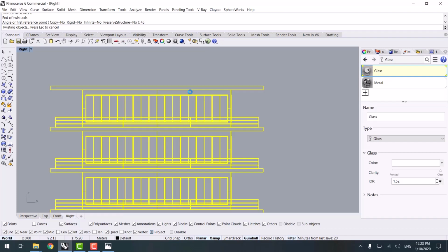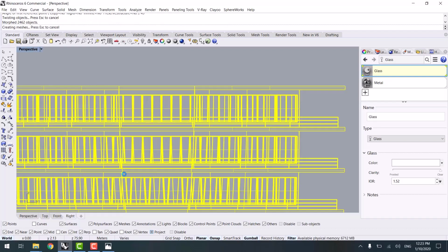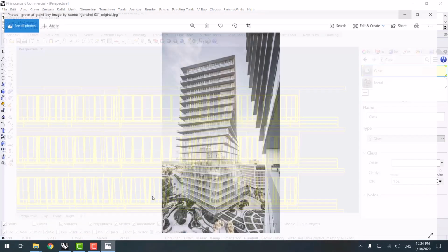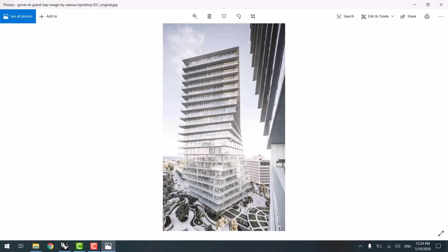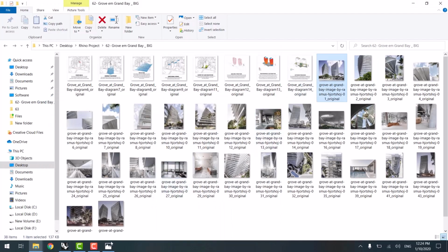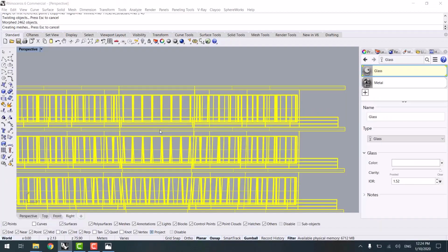And here in twist command, I should remember that I turn off the rigid option. When I put the rigid option into off state, it rotates my form as a whole. And this is not actually what I need here. And actually, you're gonna fully understand this when it starts doing its job.